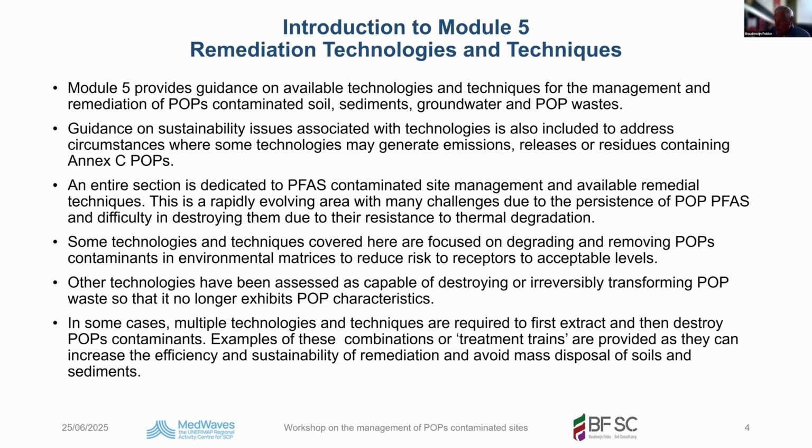Another example is if you have detected that the contaminant is on the clay minerals or on the soil particles smaller than 63 mu, as I just showed you on slides earlier, then you can separate these different soil textures on site by, for instance, hydrocyclone, and then you get the stream of the clean part of the soil and the contaminated part of the soil.